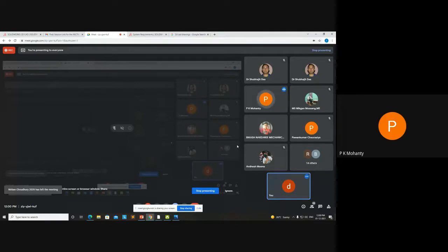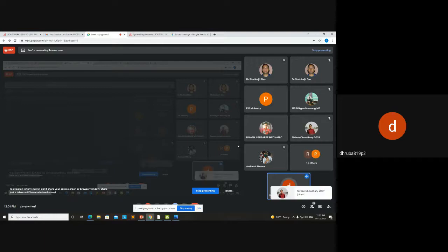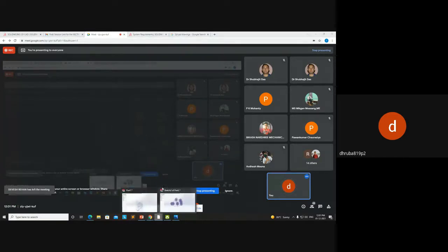Suppose you want to project any object, any model, any product. At that time you need all the views like isometric. First, you have to complete the prototype or virtual model. Then we'll take that virtual model to the drafting and annotation workbench. Over there we can take out the side view, top view, and isometric view. So there's an extra workbench for that. I'll show it over here.